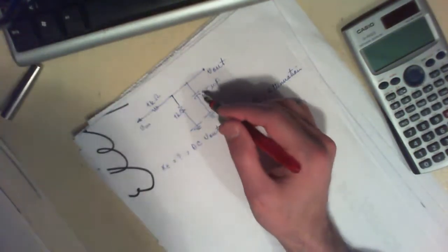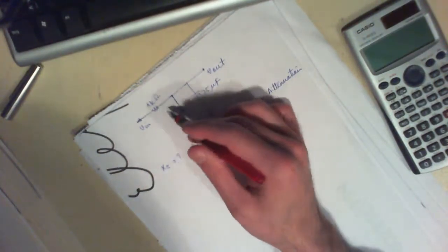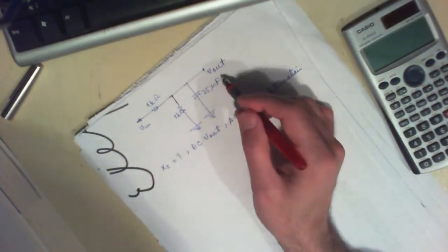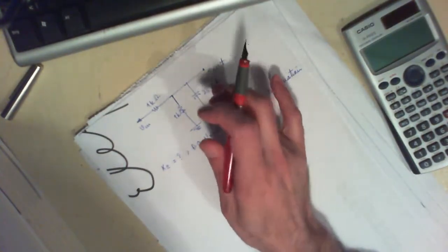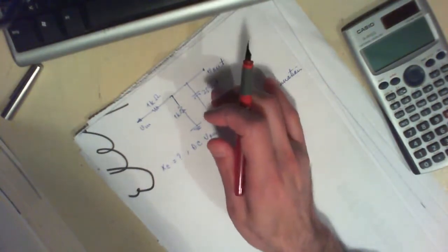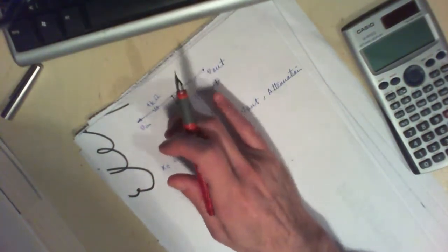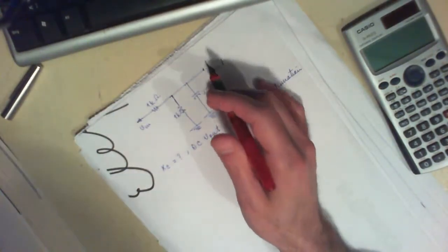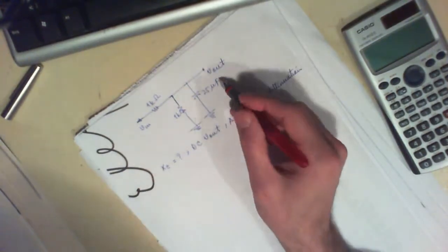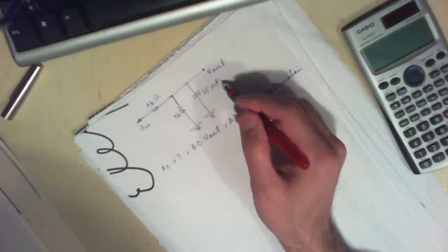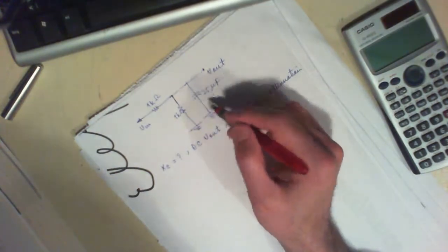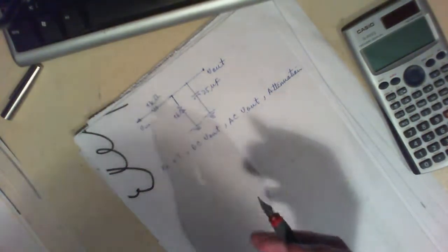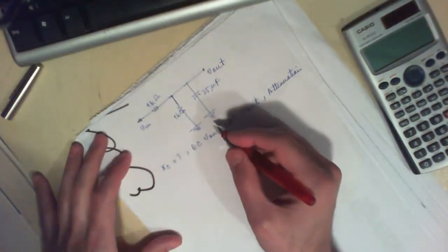Since we want to simplify this circuit without exact calculation, first you need to check the reactance of this capacitor. If that's around 1/10 of this resistor or less, then you can actually do the simplification. Otherwise, the value that you calculated would actually be wrong, like what we did in the previous video, I suppose.